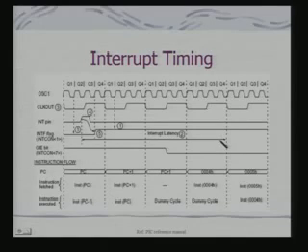Now, this interrupt latency is a very critical component, because this is a hardware latency and there would also be a software latency. These two things have to be taken into account while designing an application, because I need to satisfy interrupt constraints. What kind of constraints? Because I am making a system which is situated in the external world, and if we assume that there will be interrupts generated from the external source, I need to know the frequency with which the interrupt is expected to be generated.